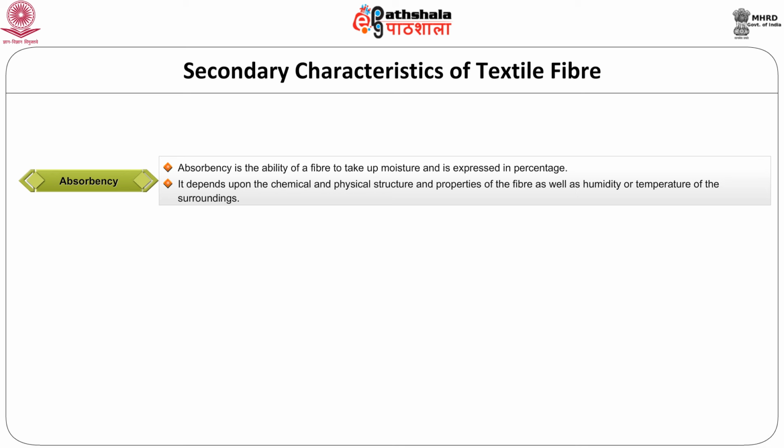The ability of a fiber to absorb moisture is directly related to wet processing processes like dyeing, finishing, washing, shrinkage, soiling and drying. Staple fibers hold more water than filament fibers since they are packed less compactly and create a sponge-like condition in the yarn and fabric. For this reason, staple fiber fabrics require a longer drying time. The fabrics made from low regain fibers dry quickly.